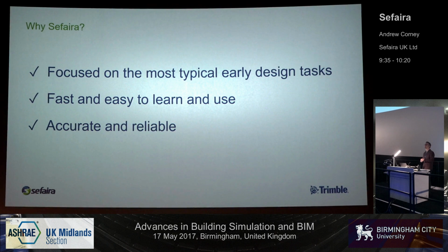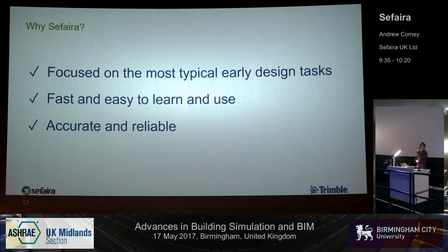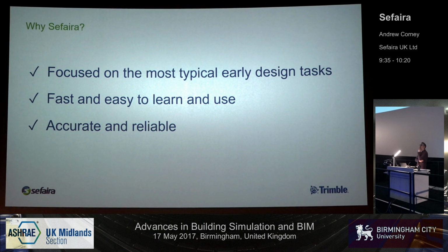Oh yes, yep. Your percentage floor areas for the natural ventilation design is still a little bit rule of thumb-ish, and I just wondered, when you test the efficacy, what part of the EnergyPlus engine are you using? Are you using the airflow network? Because, for example, a 1 square metre window is a fixed percentage of the floor area, but if I were to split that 1 square metre into 2 half-square metre windows and separate them by a height difference, I'm going to be increasing the airflow through the same 1 square metre. So I just wondered, when you're testing the efficacy, how is Sefaira calculating whether or not you're meeting the comfort levels?